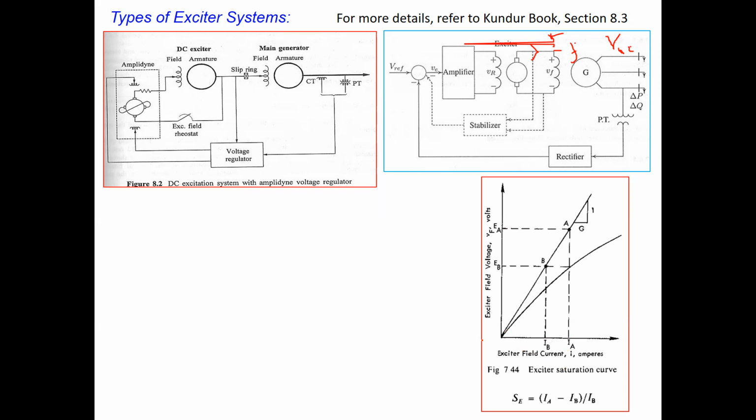And you can see that in the initial stage, in fact, the real generator characteristic, sometimes we call it the MMF characteristic here. We can also sometimes say open circuit voltage characteristic, because we measure the open circuit voltage and the variation of the open circuit voltage with respect to the change in the field current here. Because this axis is the field current. So how does the open circuit voltage vary when we change the field current? So in general, what we observe is that this is the characteristic we get.